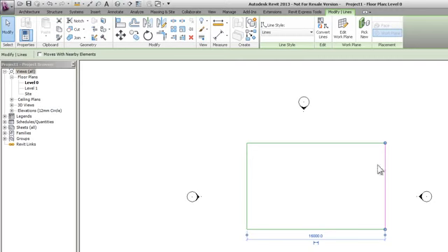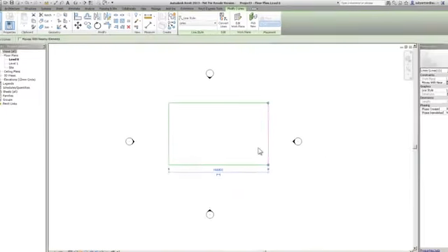They're thinking, hang on a minute, I want to know the length of this line. I'm clicking on it, but what's it? Hang on, it's showing me the length of this line. That doesn't make any sense. Well, what is it? It's not showing you the length of the line or object that you're selecting. What it's doing, it's giving you the setting out of that line or element or object that you have selected. The fact that these 2 lines are here are completely irrelevant.